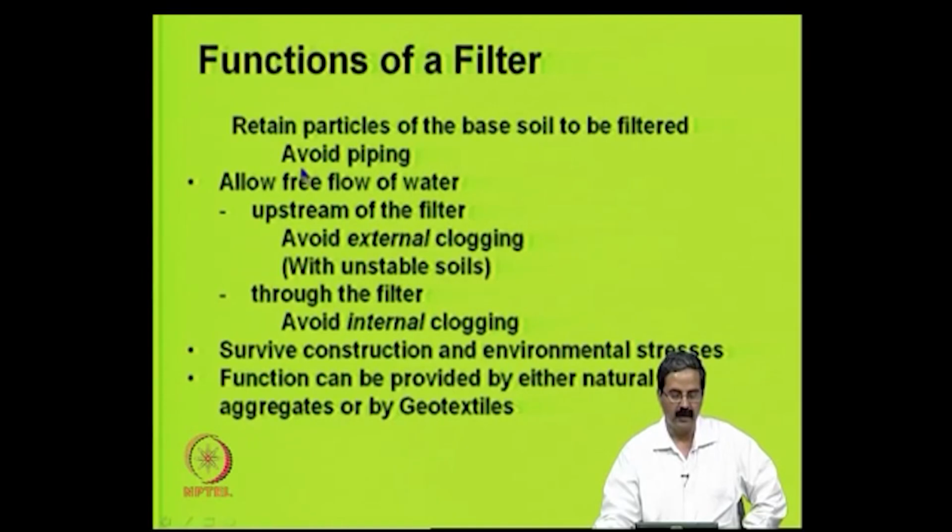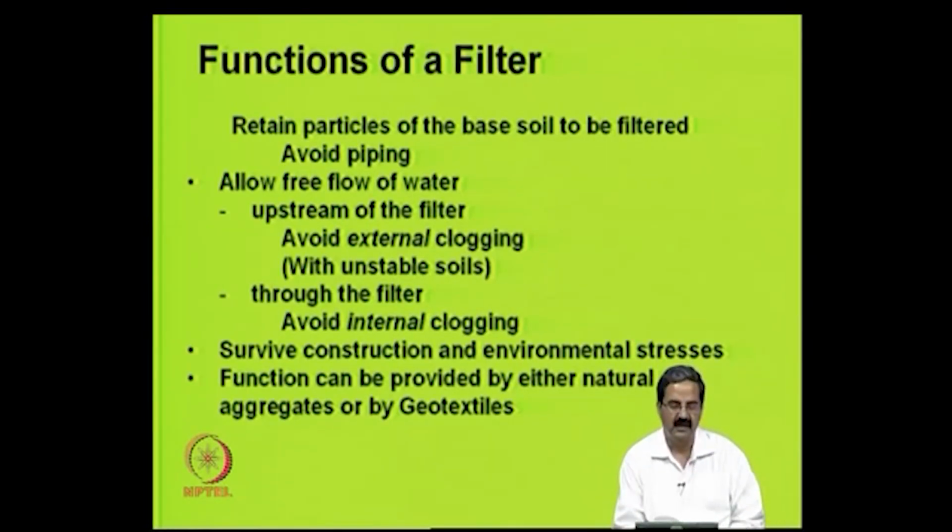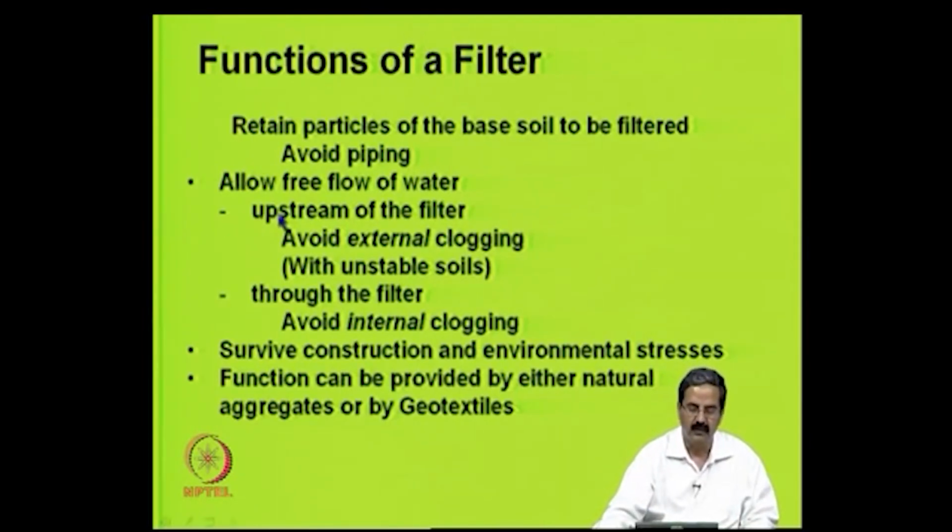Then you would like to avoid piping. In certain conditions, when water comes from the bottom, there is a possibility of piping or liquefaction, which we call static liquefaction. When the effective stress comes down to 0, piping may occur, or even a dislodgement of particles. So, you would like to avoid piping, and you would like to allow the free flow of water.